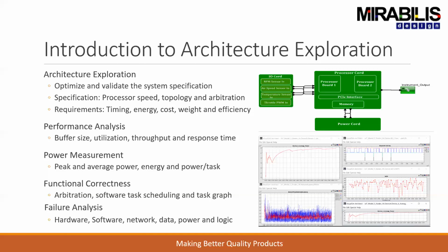Power, as we already talked about, can be an instant power, which is, at one point in time, the total power. It can be just of the DDR or the memory controller, but it can also be for the entire SoC or for your embedded system, because of course the memory controller and the DDR are only a part of your system. So looking at that overall design as well is equally important.